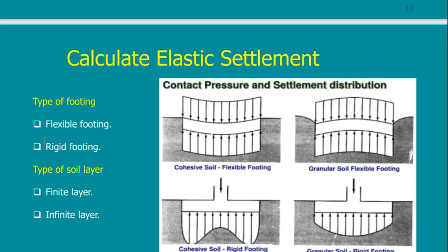But if I give you, instead of this plastic piece, a steel piece or a concrete piece, it will be rigid, and when you stand on top of it, all of the soil below this piece will be compressed because it is rigid. So depending on the type of the footing, the behavior of the footing will be different.